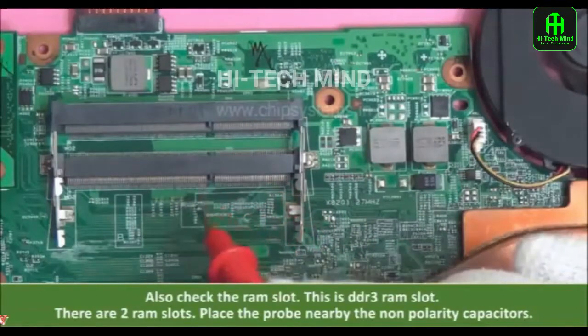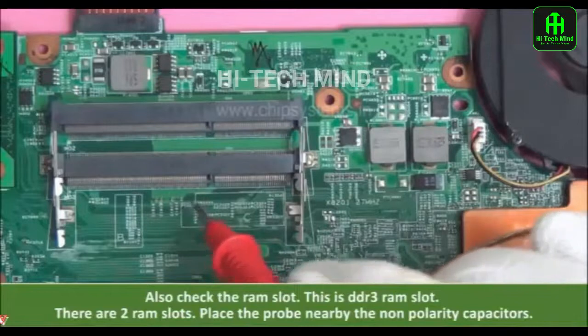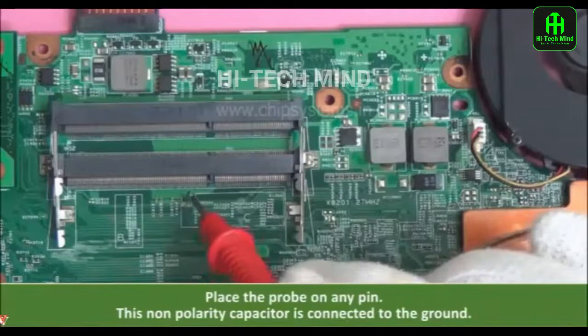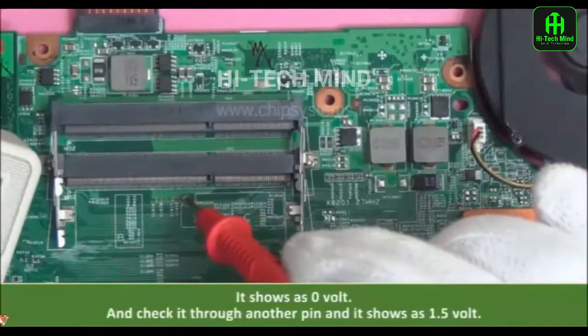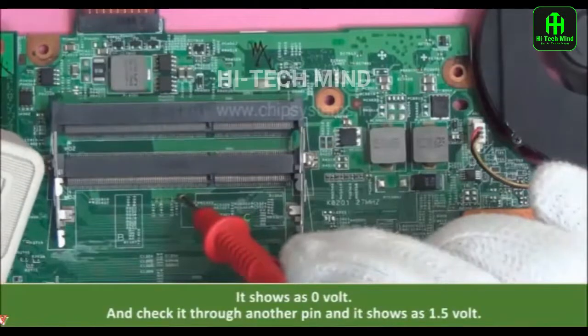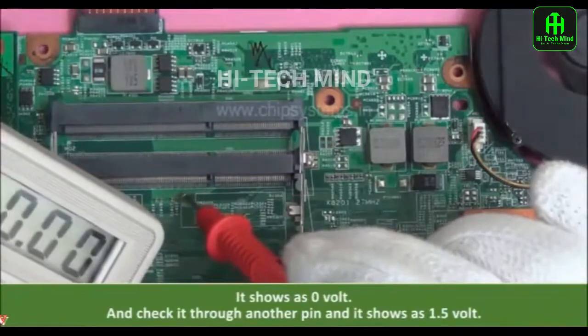Place the probe nearby any polarity capacitor or non-polarity capacitor. Place the probe on any pin. This non-polarity capacitor is connected to the ground. It shows 0 volt. And check it through the other pin and it shows 1.5 volt.